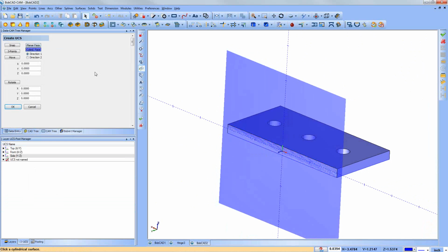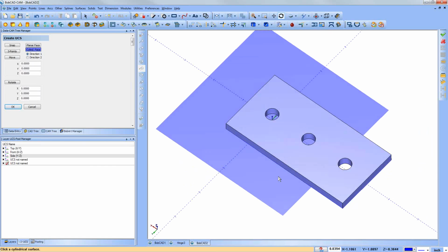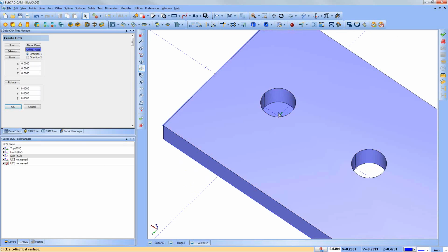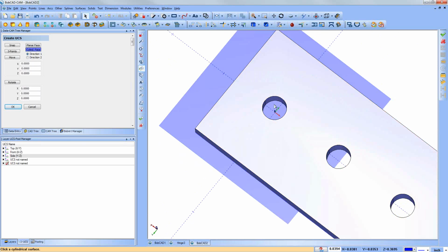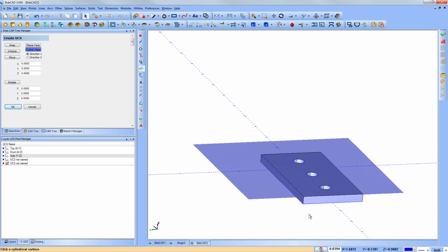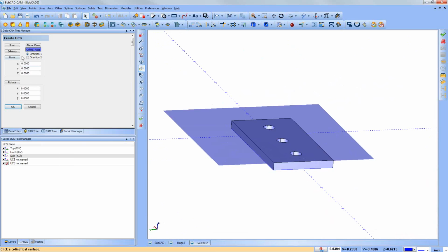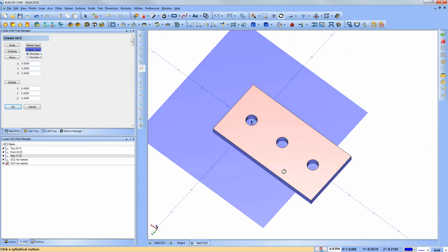Cylindrical face, this will allow me to pick off a cylindrical face, and then we have direction 1 and 2, which basically means which way the Z is going to be pointing. So if I want to create a plane there off the middle of this cylinder, pointing up, direction 2 will go down. And then we have another one called 3 points. 3 points and move are the existing ones. So let's look at the move option here for a second.